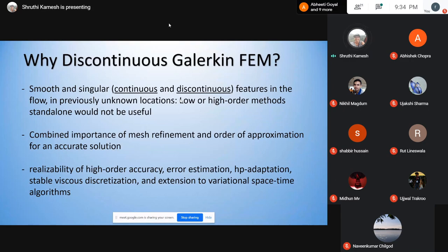You model these using certain basis functions, right? Now, what the Galerkin method does is use the same functions of approximation for both the field variable as well as the weighting function. That's essentially what it means. And it simplifies the equations, it simplifies your understanding a lot when you use the same functions for both, and it makes life a lot more fun. So that's what Galerkin did, and you would find that when you first start learning finite element method, Galerkin is the first way you get introduced to it.